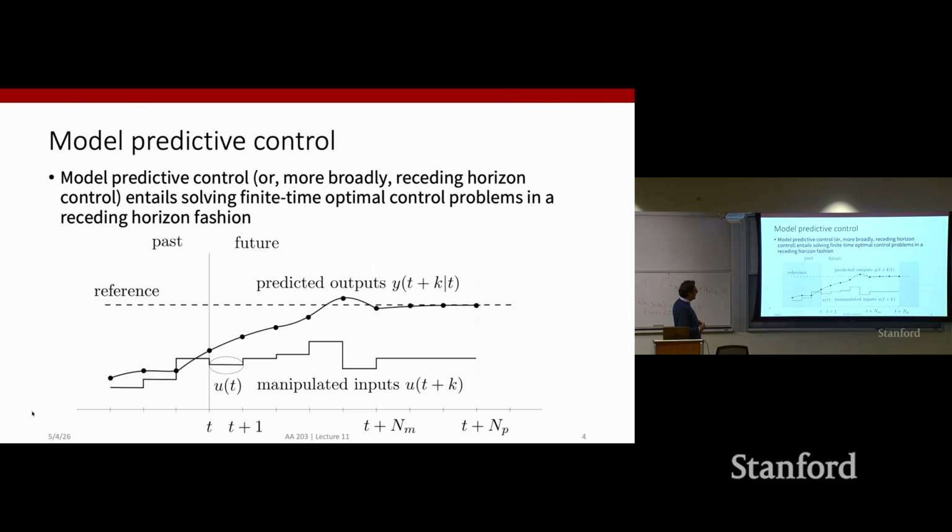So what does MPC do? MPC measures and keeps track of previous values of the states. Based on that information, based on information about the dynamics, based on the control and state constraints, it computes a control profile. Here we're assuming that we are solving the problem in discrete time.